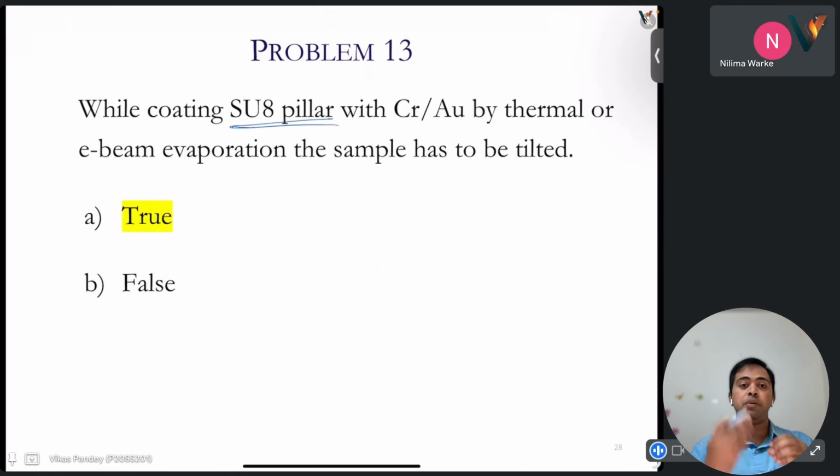In this case, since it is a pillar structure, we have to go for some other process, and here we are talking about MEMS based sensors. In MEMS based sensors, we will have some 3D structures, with depth, and some bigger mechanical structures like pillar, cantilever, and so on. In this case, we can have some modification in the general microfabrication process.